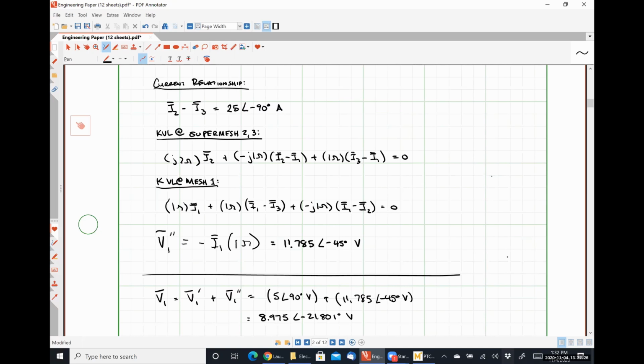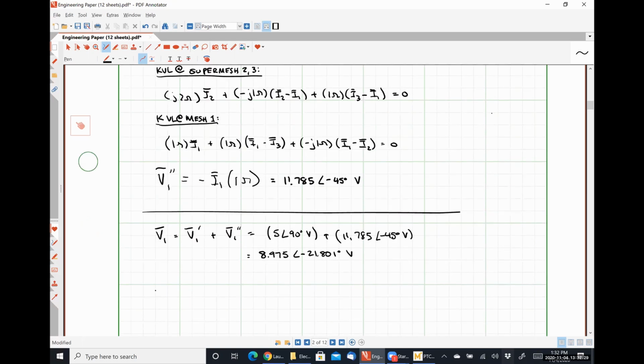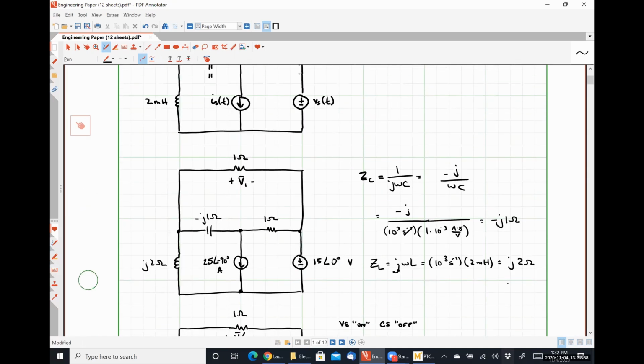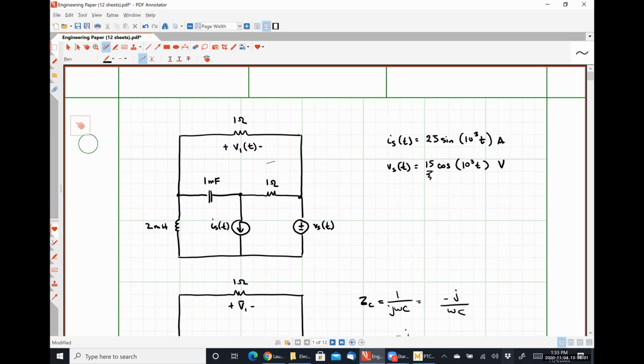And now the $1 million question, which I've actually been forgetting to do. How do I convert that answer back to the time domain? Sure, you couldn't put it better. So to get our phasor representation, we took, say, the magnitude of this guy, 15, and the phase angle of 0, and that gave us our frequency domain representation.